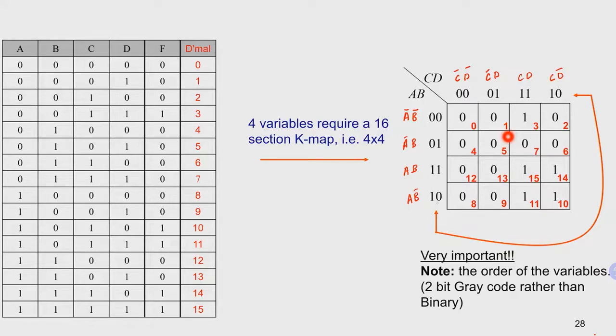This is another way of writing it, but it's easier to write 00, 01, 11, 10. So in the following slides, I will use 00, 01, 11, 10 as the axis instead of writing down the variables as A and B. And then the corresponding cell related to the binary number of the inputs A, B, C, D, I have listed in red.